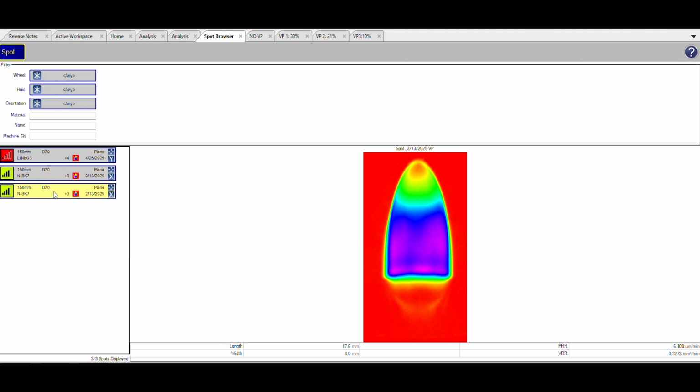results. We all have had situations where we have taken a spot and the solve results tell us that that spot is not ideal for polishing the error that we would like to correct. And we have had to go back, set the part up, take new spots, take new metrology, and reevaluate. One way to make that process more efficient is to take variable plunge spots from the beginning.